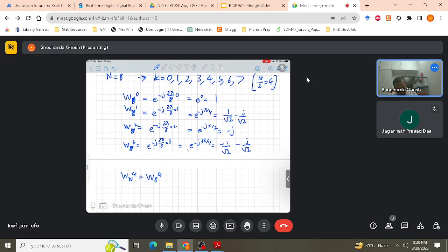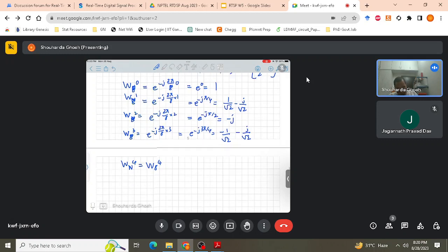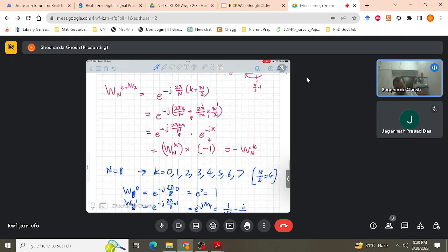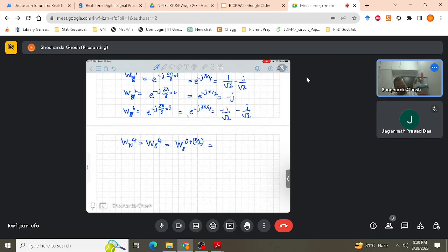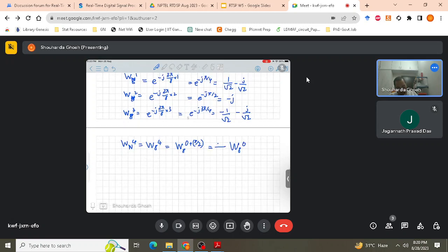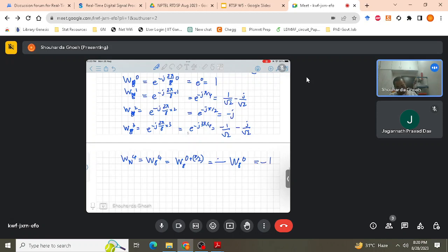W8 of 4 is how much? W8 of 0 plus 8 upon 2. Okay, and what did we see over here? We saw that Wn of k plus n by 2 is minus Wn of k. So what do we do? It's the minus W8 of 0. What do we get over here? Minus 1. See, we did not have to do any extra calculation.